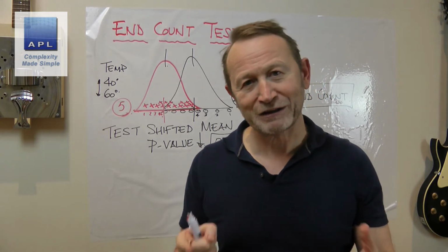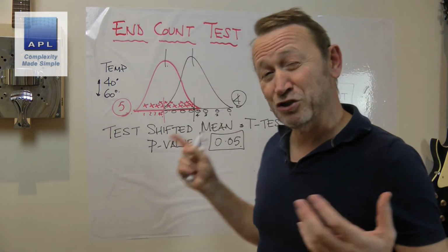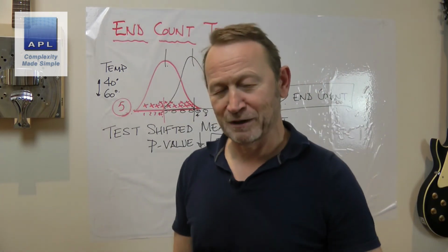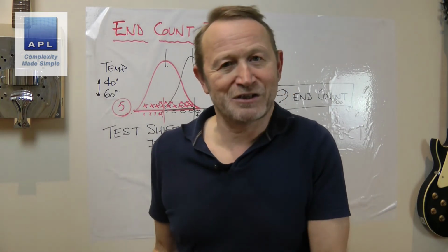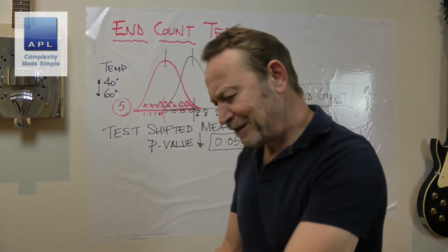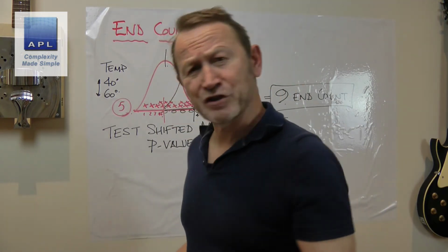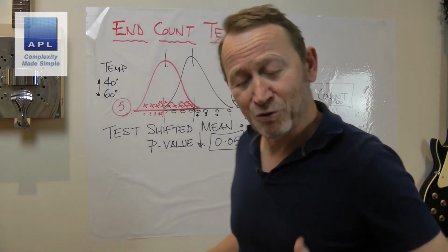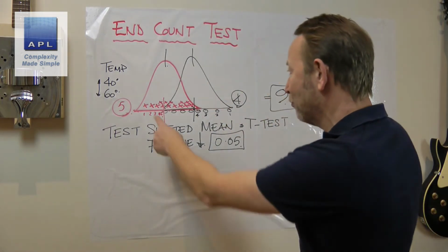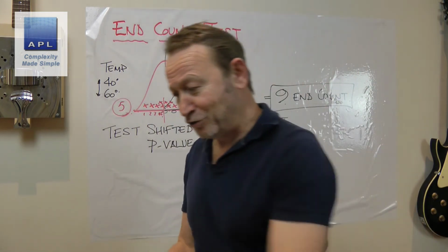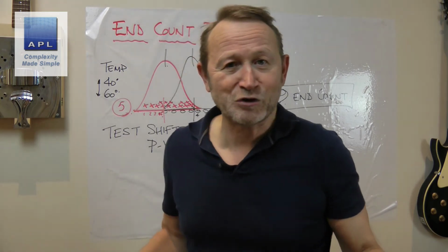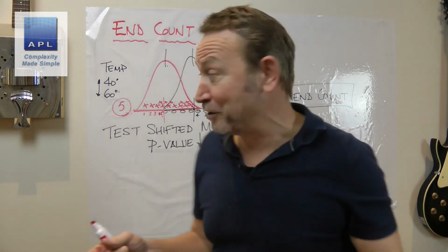Now it's a very practical thing that you could do. You could do this on a machine. So if you were stood at a machine without your laptop, without all the maths to do a t-test, and you were just thinking, oh, I wonder if I made this change, I wonder if the surface finish would get better. Well, you could take the surface finish of 30 data points before, maybe the red, then you decide to change the speed, or you put a new cutting tip in there or something, some simple change that you're going to make.